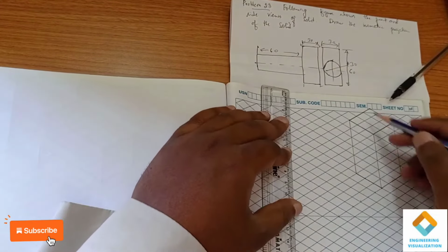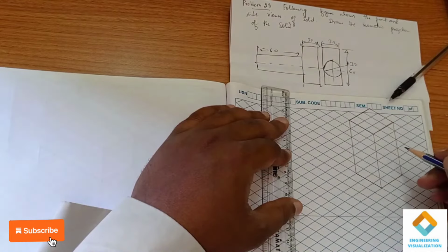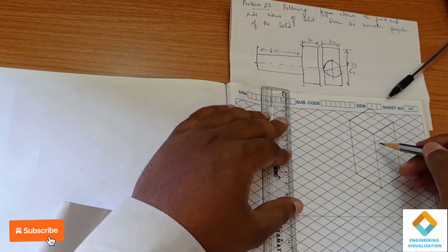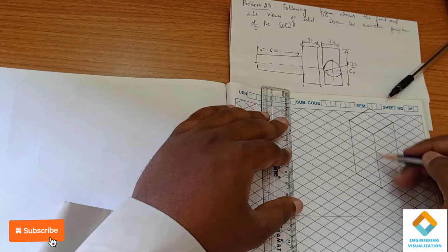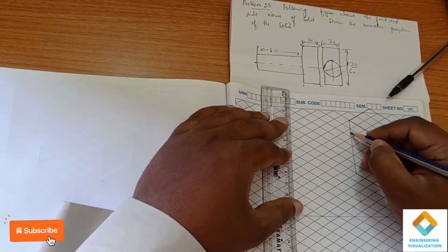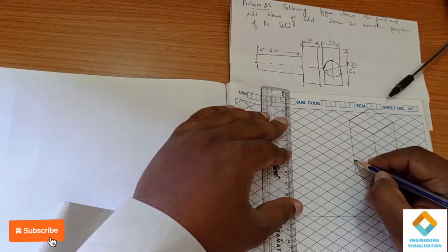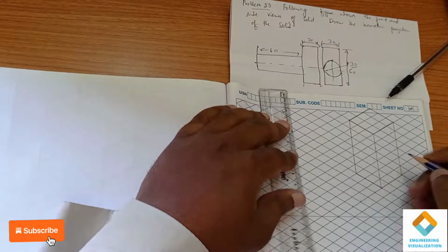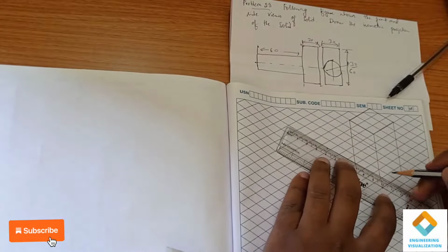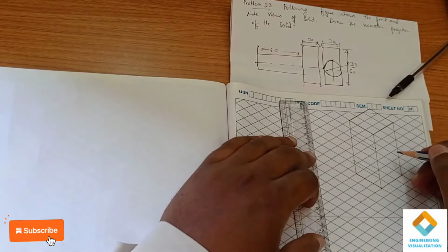Now we have to construct this cylinder. Cylinder of diameter 30, length 60. You can see the diameter 30 and length 60. So diameter 30 means here we have 60, so 1.5 boxes we have to subtract, 1.5 boxes on either side. So we get a box here now.